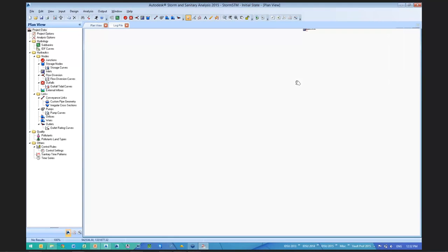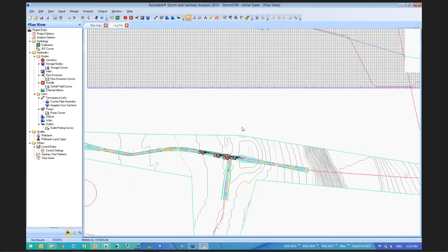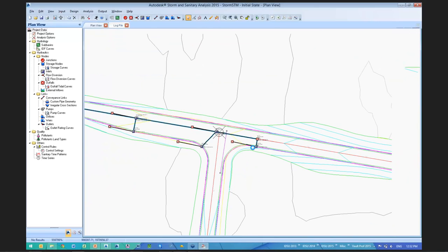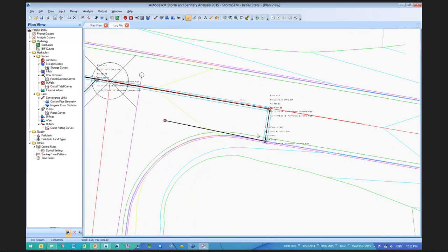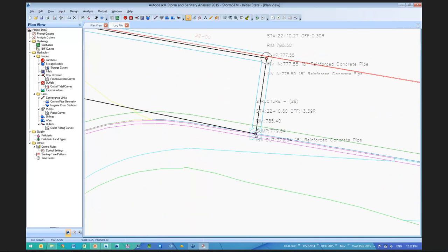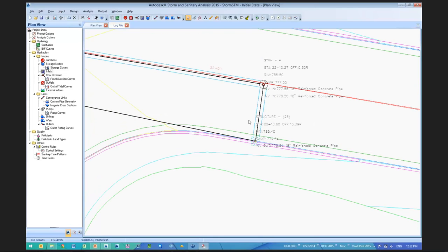And so looking over here, I zoom in, I'll see that same DWG basically referenced back there, and now I have an SSA catalog here, okay, and so here's that catch basin, that inlet, okay. What dictates what kind of structure it gets in here, because this is different, it's not the exact same structure we have, these are mapped to different parts. But to make this fairly seamless, you have to say what is mapped to what.